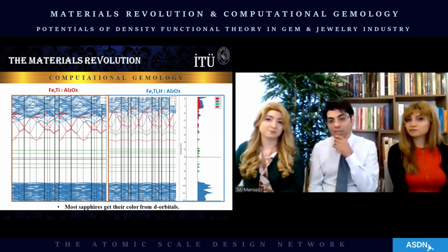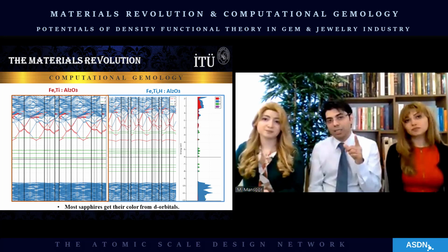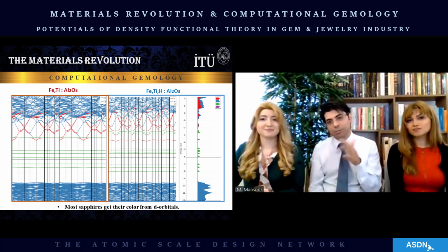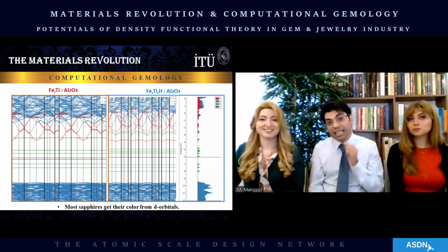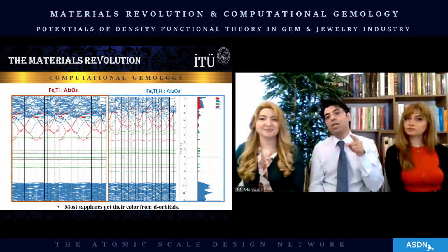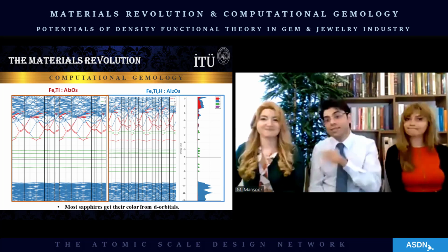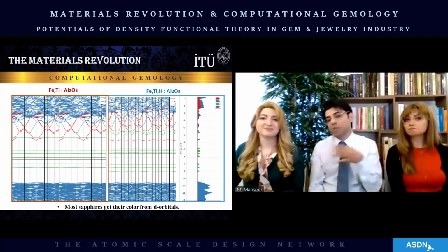Something important has to be considered here. We should note that even the slightest addition of an element inside the solid solution can change the bond length and influence the energies of the d orbitals, even if the atom in question has no d orbitals in itself. That would in turn change the response function, and it would also inevitably change the optical behavior of the material.